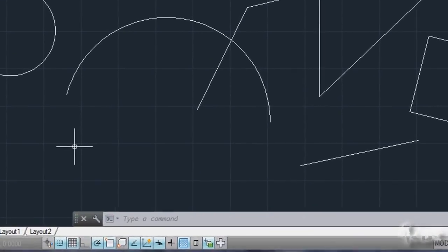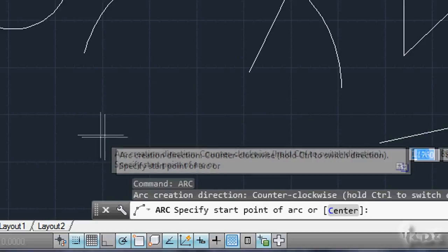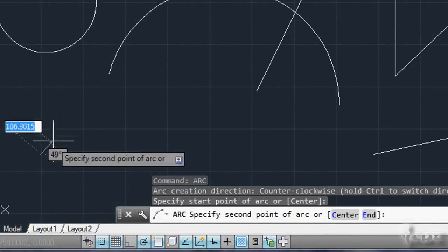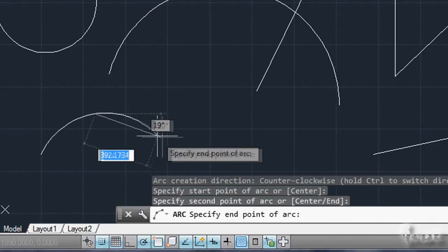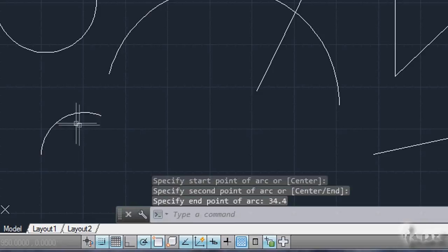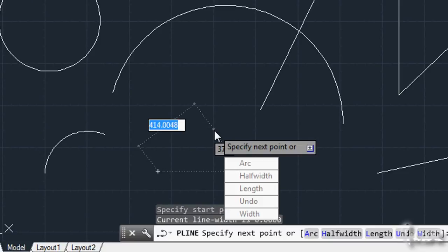To redo the previous actions, just press the up arrow until you find the command you need. For example, if you want to draw an arc again, press the button until arc shows up. The white slot can be used to enter precise numbers too, which is fundamental for professional projects. Instead of setting a point or distance using the pointer, you can enter your precise value. Moreover, commands can be chosen using the down arrow key. Choose the command you prefer and then press Enter.